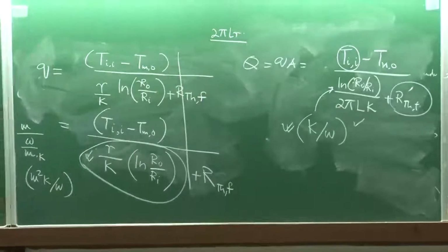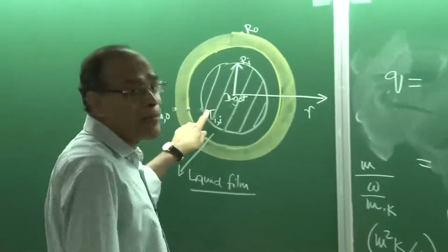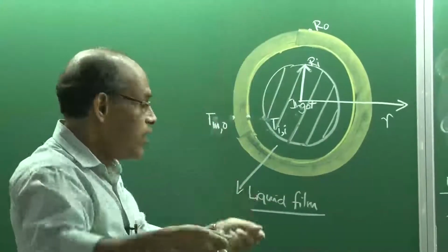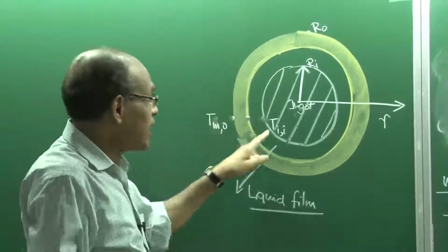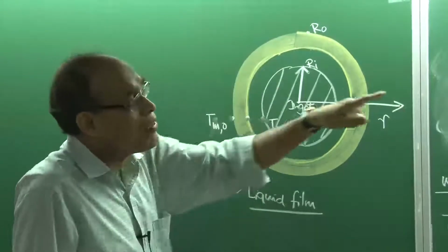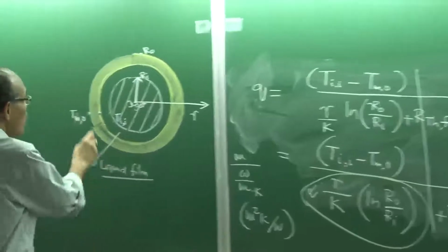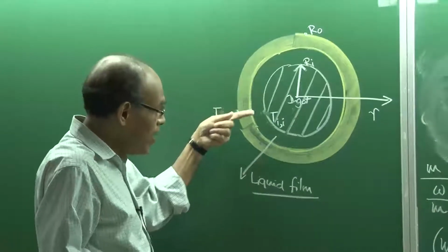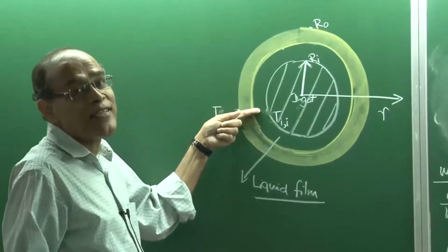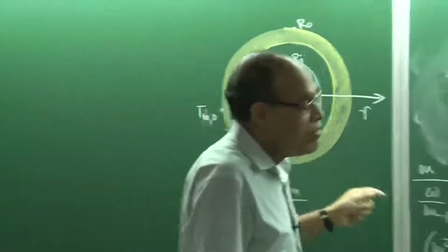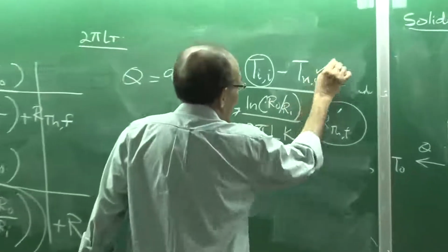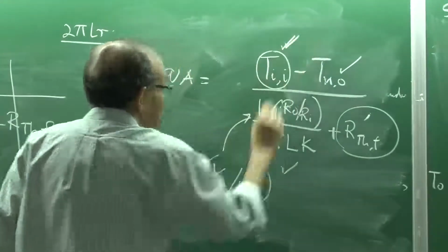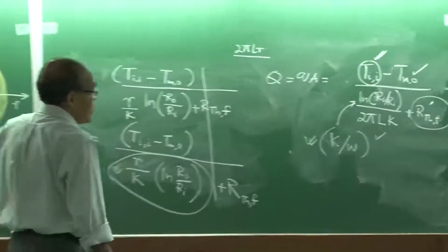This is known only at the instant when, for example, because this is the inner temperature, I have no way to access it. It is only at the instant the mold is stripped, when the ingot is exposed, that I can find out a temperature. Or, on the other hand, one has to have a thermocouple inserted inside the mold by drilling holes, touching the surface and measuring the temperature itself. So this is again measured at the outside. This can also be measured or inferred at the moment when the ingot is stripped.